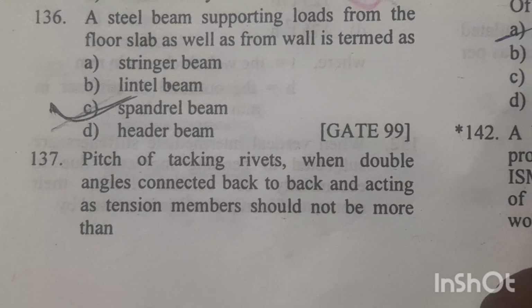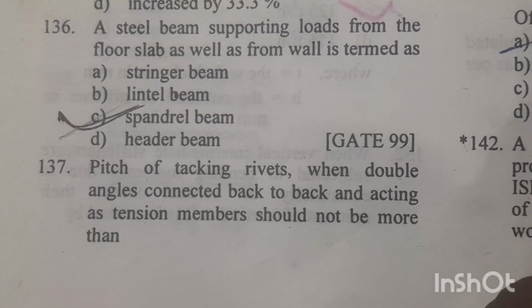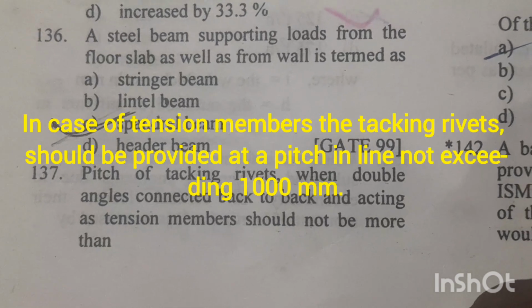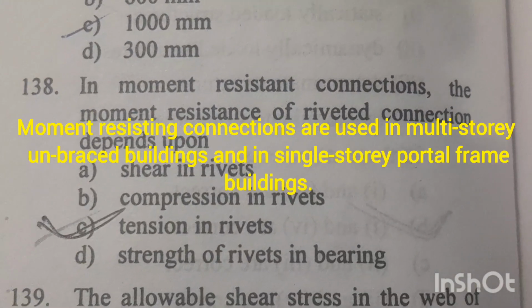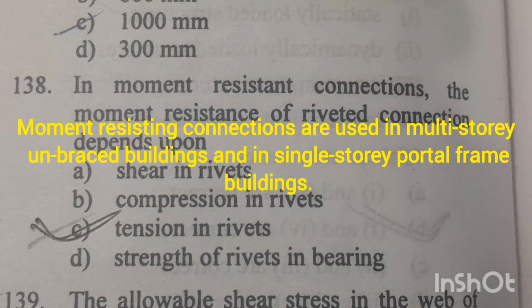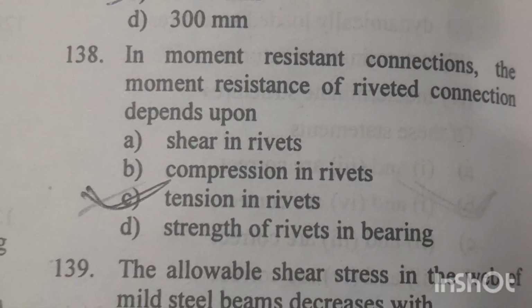Question number 137. The pitch of tacking rivets when double angle connected back to back and acting as tension member should not be more than 1000 mm. Option C is right answer. Question number 138. In a moment resistant connection, the moment resistance of riveted connection depends upon tension in rivets. Option C is right answer.